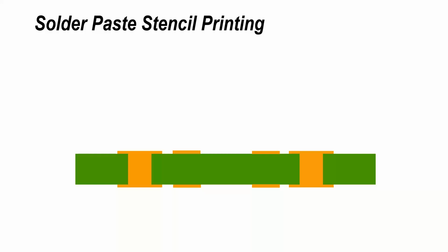So when we're printing solder paste onto the surface of a printed circuit board, we start with a board and we print directly on it with a stencil. A stencil may be 6/1000ths of an inch, 5/1000ths, 4 or 3/1000ths of an inch in thickness. So we're looking at 125, 100, or maybe 75 microns. And the stencil material varies. Stainless steel, very popular, but also nickel form stencils.